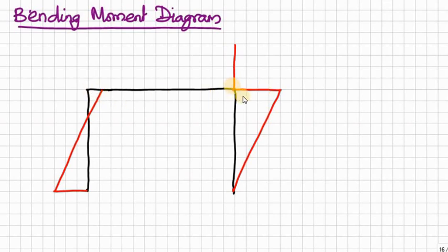For the BC beam, this is again just the opposite moment here, and here also MB in the opposite direction. Therefore you have to join these two. I use a different color too, so that we can easily identify the moment diagram for the different members.